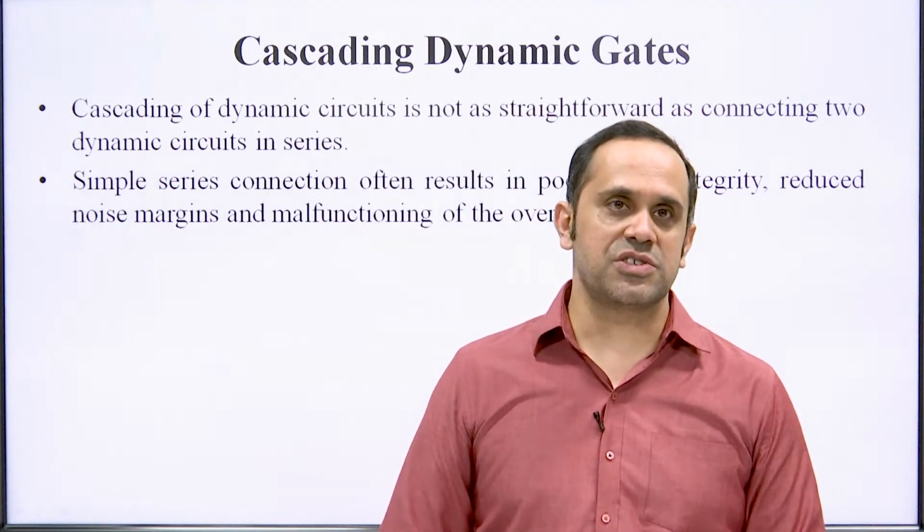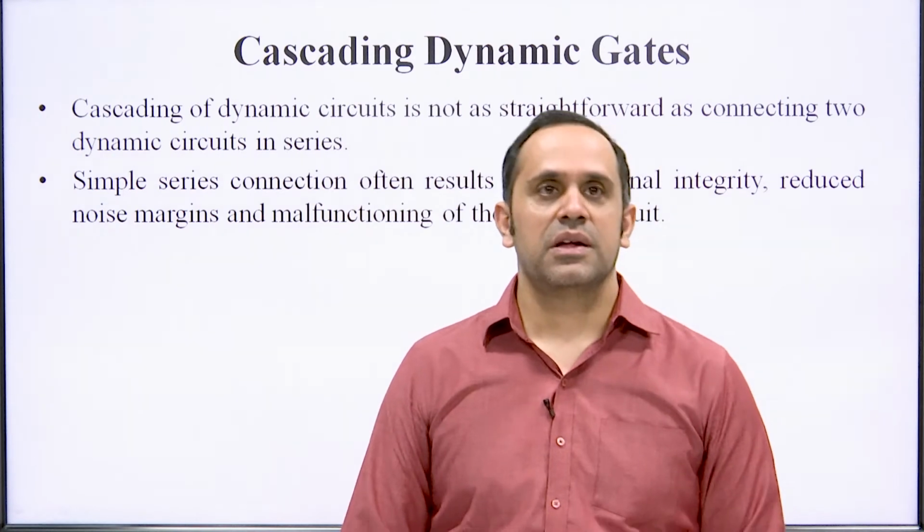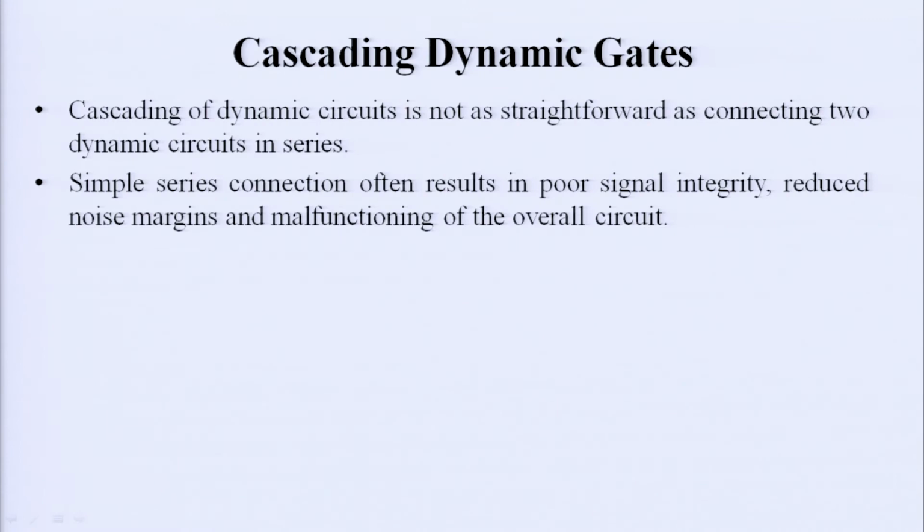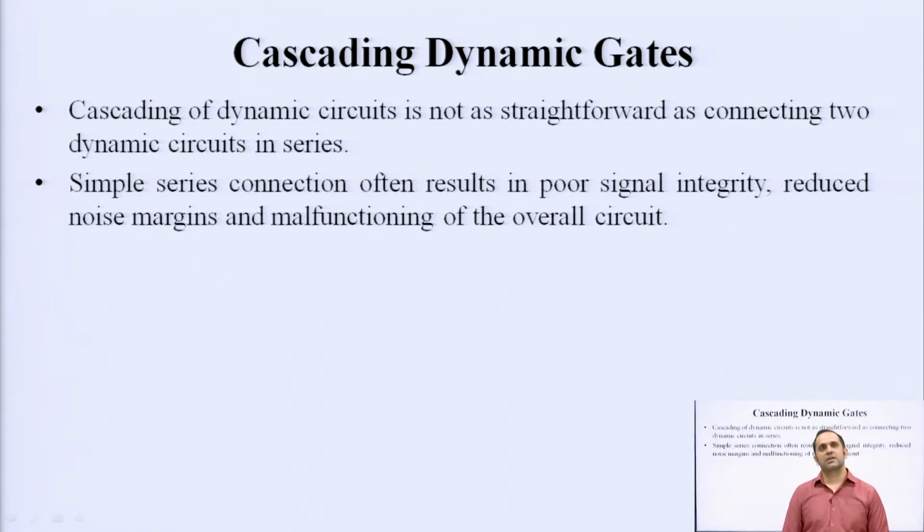When the clock changes its polarity and goes high, the evaluation stage kicks in, and whatever logic you are trying to implement is tested and the output is connected to the load capacitor. In the evaluation stage, the output can either make a transition from 1 to 0 or stay at logic 1. This way a dynamic CMOS circuit allows you to have a lesser number of transistors for the same logic operation as compared to a static CMOS circuit.